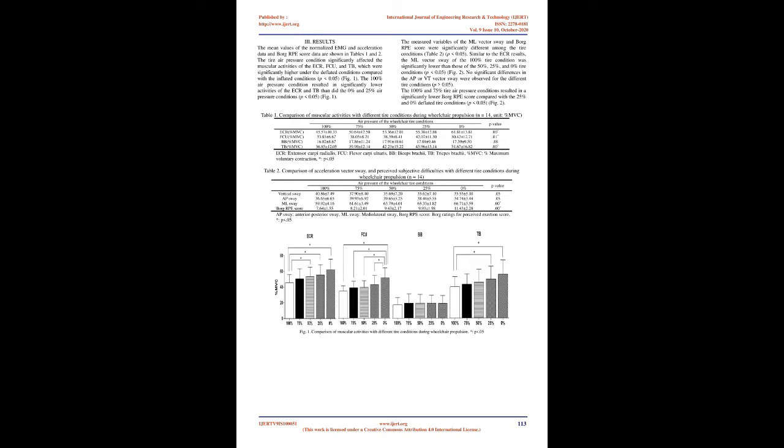Surface electromyography, SEMG, data were collected using a wireless surface EMG system, Wireless EMG System 1000, BTS, Milan, Italy. The SEMG signals were sampled at a 1000 Hz frequency. The data were computerized using EMG acquisition software. Band pass, 5-450 Hz, and notch filters, 60 Hz, were used. Four channels of surface electrodes were attached on the dominant right side of each subject parallel to the muscle fibers.